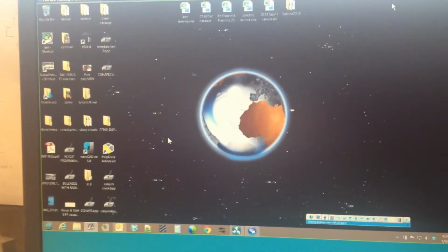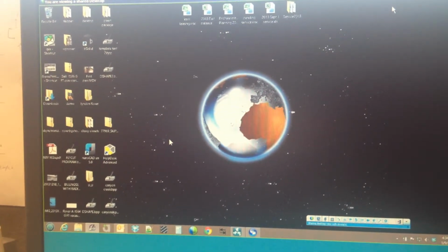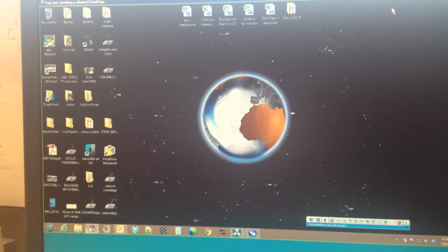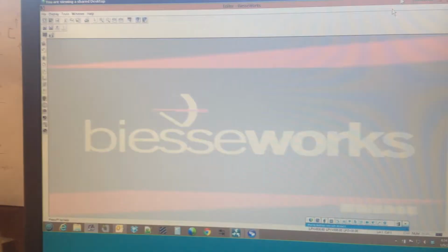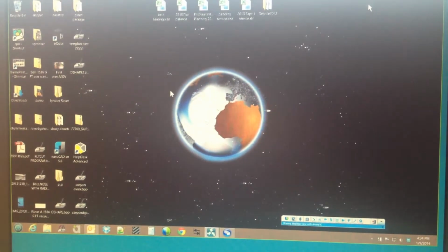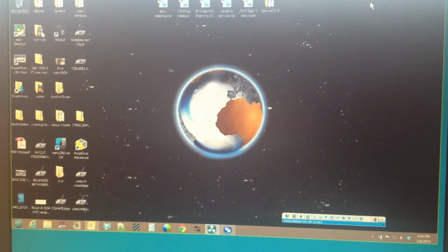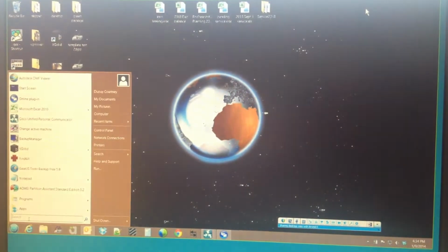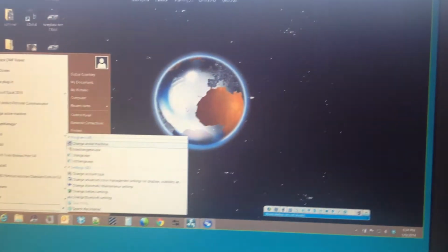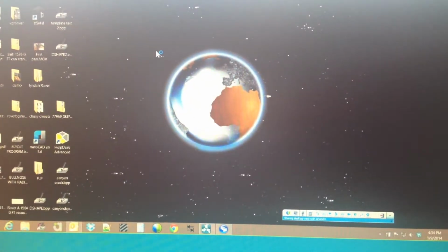Actually, for the skipper, normally we don't program the tool name at all. We program the diameter and the type, so that when you do the double head, it can do it automatically on the other side. Did you get that, Matt? Kind of. So you don't have a named tool in there because it thinks there are two different tools, right?